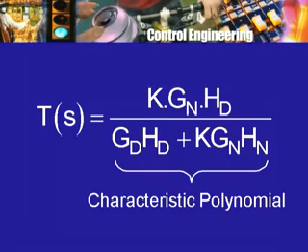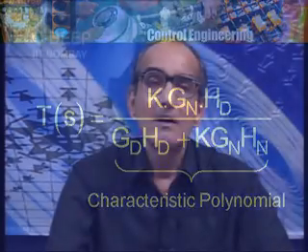So, we have to look at this characteristic polynomial, but in the Cauchy principle of the argument approach, what you have is not a polynomial but a ratio of two polynomials, and then you have the number of encirclements and so on. So, how to take care of that? Now, that can be taken care of in the following way. This is where some confusion is possible, so you should pay attention.